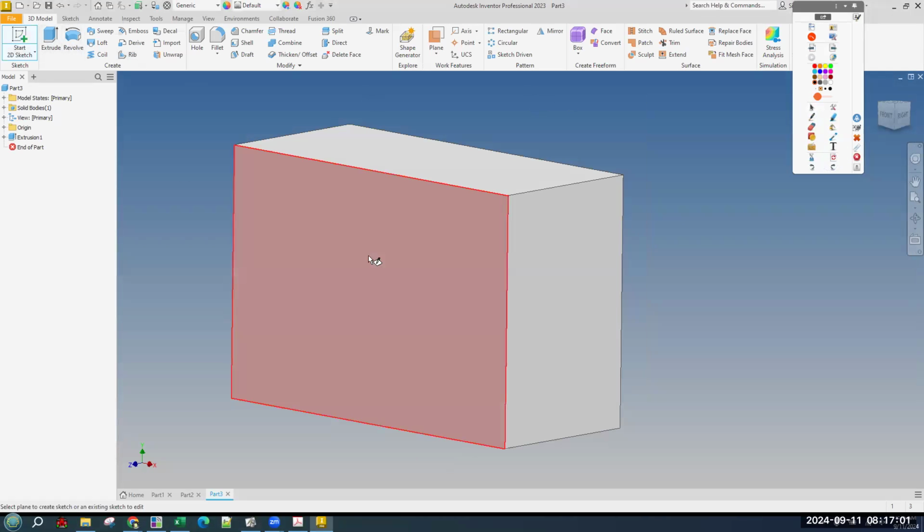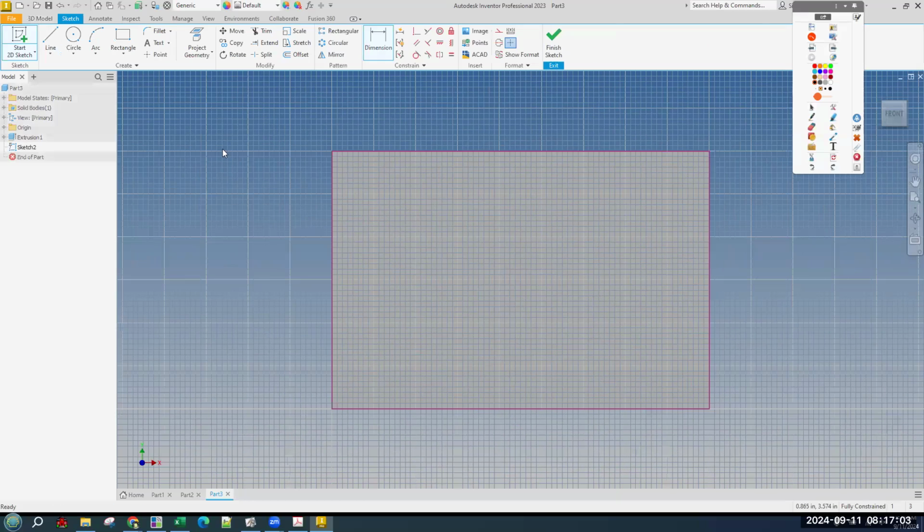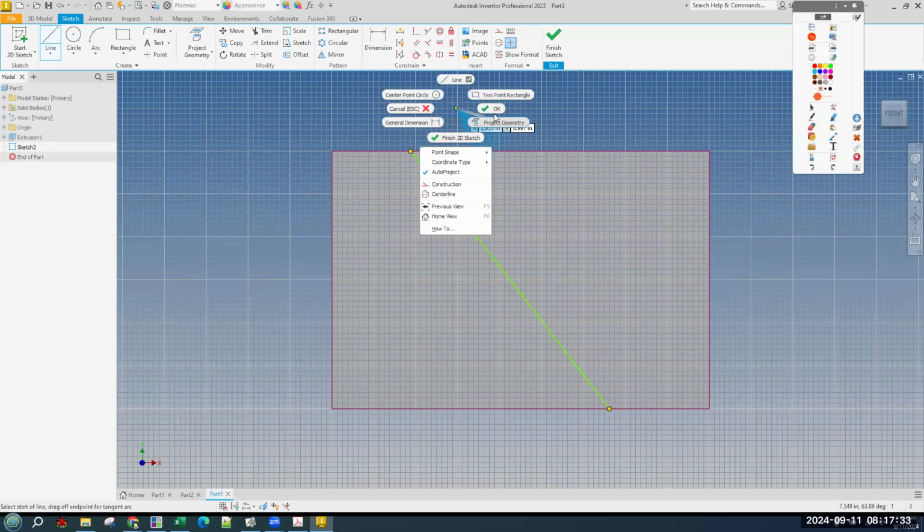And so let's sketch on the front. We need a line that snaps to the top edge, like I said, but not one of the exact center points, not where it is green, just somewhere on the edge on the top to somewhere on the edge of the bottom. It doesn't matter if you put it over here and snap it. Our dimensioning is going to change it. In sketching, in modeling, dimensioning locks in sizes, but you can also change sizes. It changes and locks it. So we have our line, and we can do right-click OK.